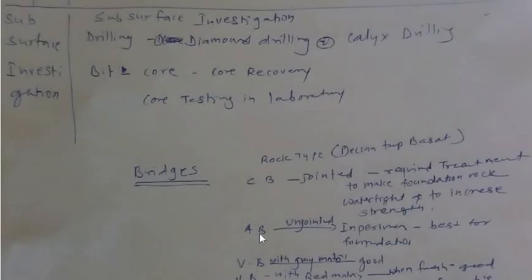So geological investigation is carried out for obtaining data required for determining the foundation level of the bridge, scour depth, safe bearing capacity, that is SBC, buoyancy, etc., and to collect samples of foundation material for laboratory testing also.